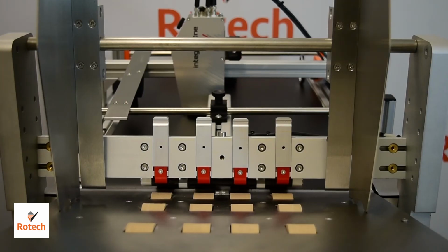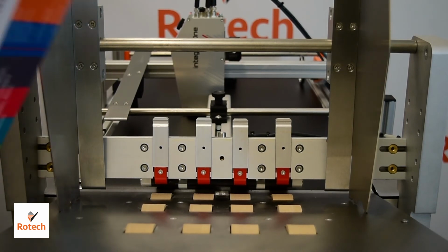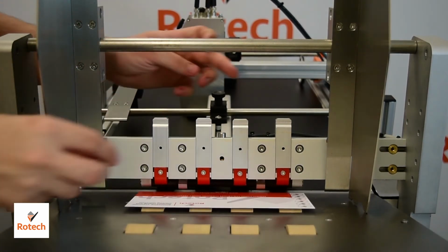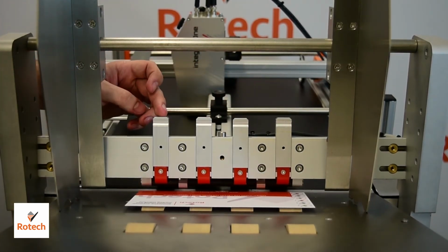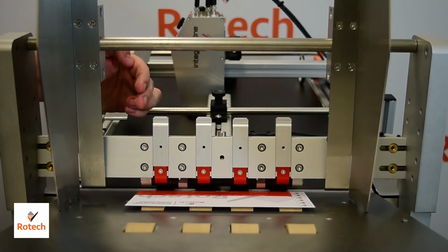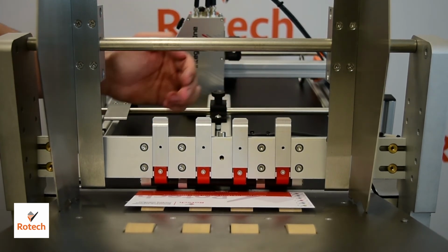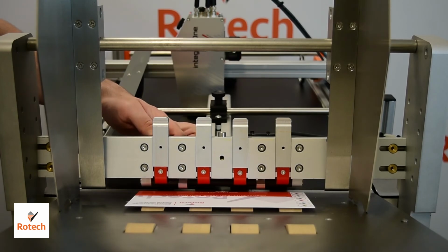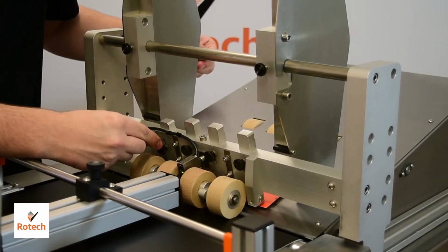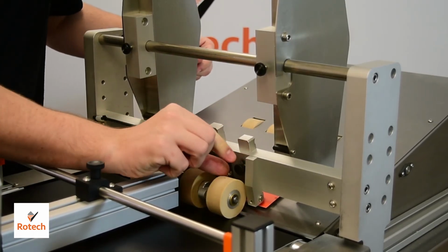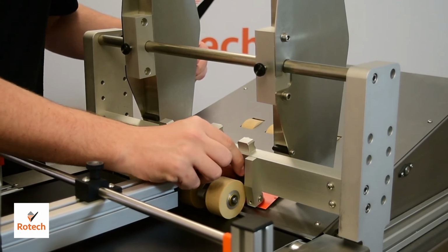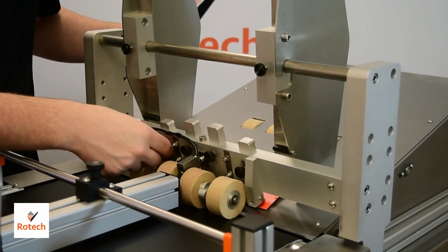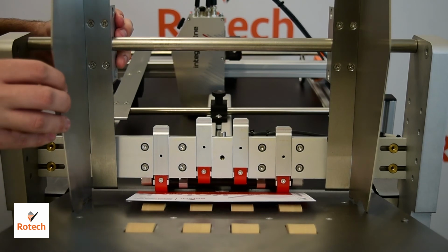To set our product up, we're going to place the product on the rollers. To set the gating, we have these 4 fingers. We only want to use 2 of these fingers dependent upon the size of the product. As this is a larger product, we're going to use the 2 outside fingers. Simply loosen off the screw on the back and then let them drop down. Once they've dropped, tighten them back in place. Gravity is acting as your main aid here.